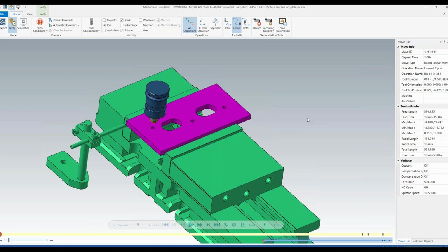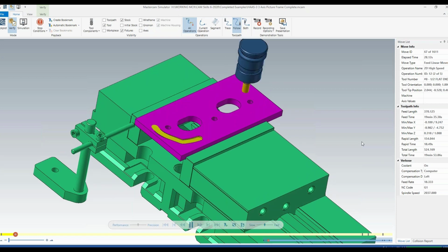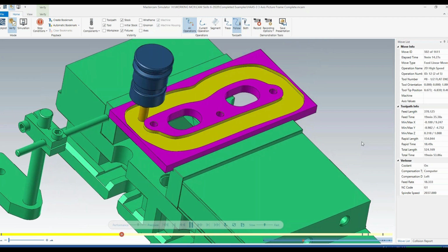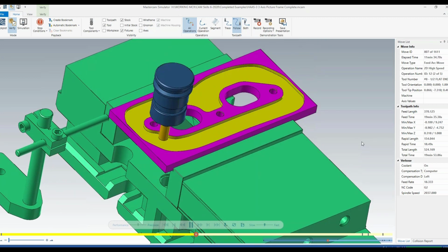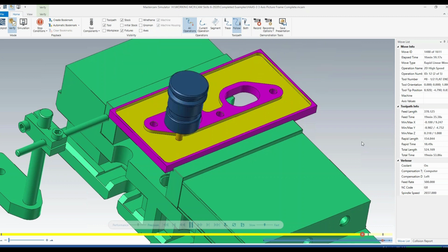I've already got the first stock model created. I'm just writing toolpaths and adding stock models and changing what I want to see and verify. So now I should see essentially that part suspended by those tabs when I'm done. Literally just flipped the material over and machined the back side.